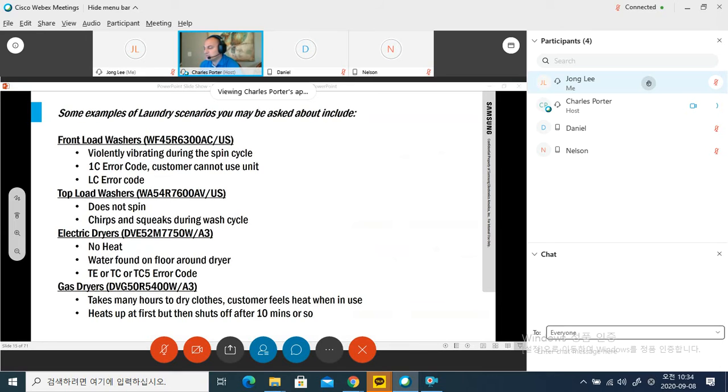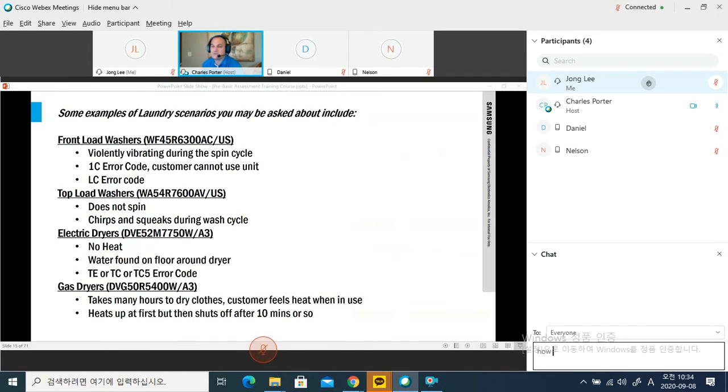But you'll go to your heater box. You'll check your TCOs. There's 2 of them on the heater box. And then there's also a TCO on the blower. But first you'll check the heater box TCOs, make sure that those are closed. Check for continuity. Obviously unplug the unit first. And then you'll check continuity at your heater coil. You'll physically look inside the heater box, make sure the heater coil looks okay. You can also take a resistance reading there as well. But generally speaking, if it has continuity, it's good to go. Especially if you take a look physically and it looks good.